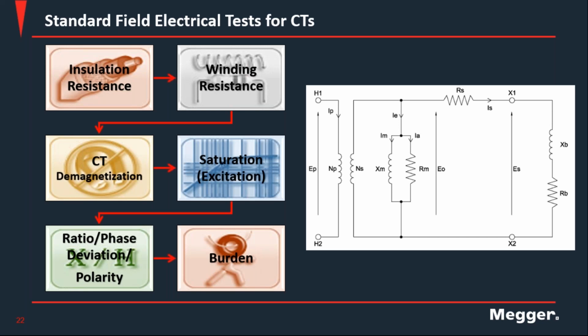So the FS, that's le facteur de sécurité, security factor in English. That's a parameter that is used in IEC for, I believe, metering transformers, and it's the maximum voltage that can appear on the secondary of that transformer. And the way we measure it is we basically extrapolate on the excitation curve.